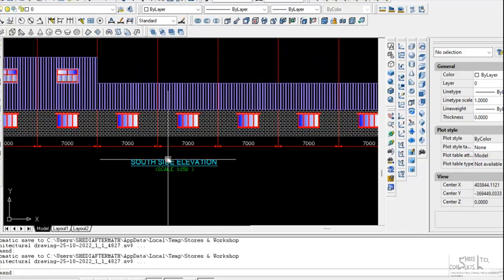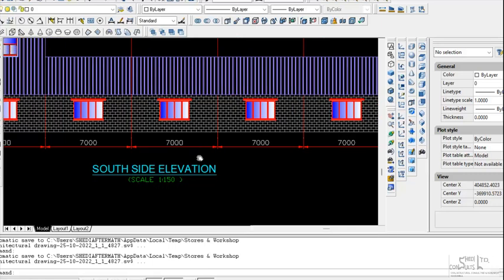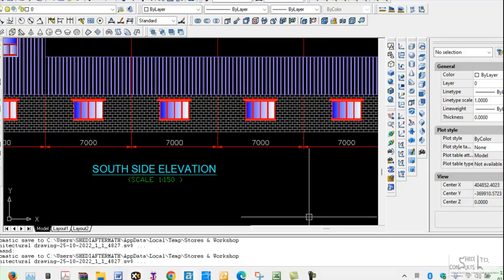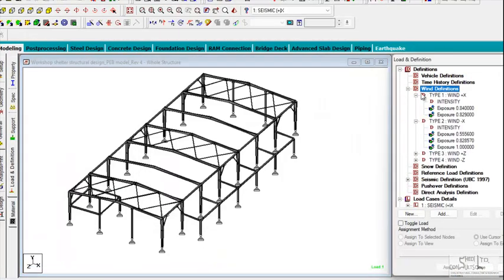Now, to determine the wind loads on closed areas, what STAAD will do, if you use STAAD to determine your wind pressure, I'm using it as an example. So if you use STAAD to generate your wind pressure, you will generate it after specifying the code specific parameters.